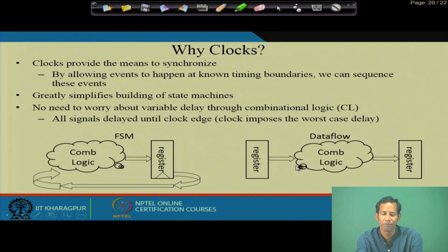After that, in every sequential circuit, the main important factor is the clock. Why the clock? Basically, the clock provides the means to synchronize the circuit. Synchronization in a digital circuit means the operations should be performed at a particular instant. That means within a particular clock period or a particular event, every circuit will start operation, delivering the outputs or capturing the inputs. So, it depends upon the operation or the event of the clock.